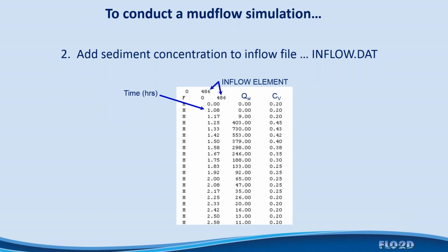concentration by volume for the entire event, which may be appropriate for that removal of the log mill in that movie that I showed you before. That was pretty uniform. It got a little bit more fluid towards the end, but something around 45 to 50%, depending on which of the samples you used from table 9. And if you wanted to model that mud flow event where it removed the log mill, I would definitely consider the Glenwood sample number 4.